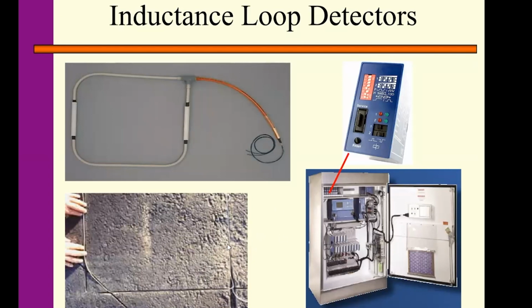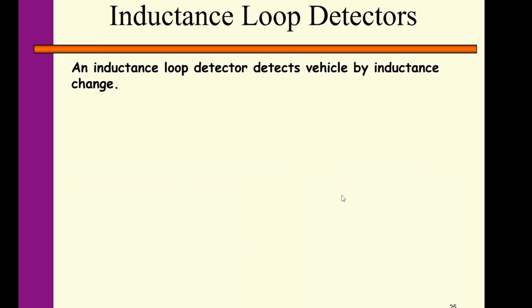And so when a pedestrian or vehicle occupies the top of the sensor, it triggers the signal, triggering the inductance decrease. It can be captured by the detection card, converted into vehicle counts, and input to the controller. So that is the basic mechanism of how the inductance loop sensor detects vehicles by the inductance change.